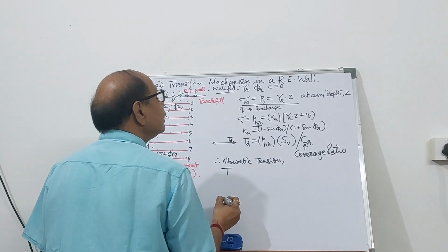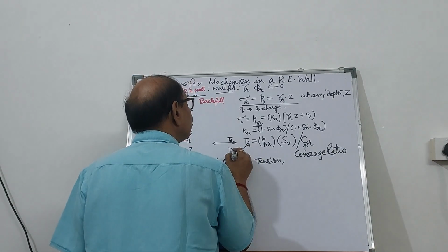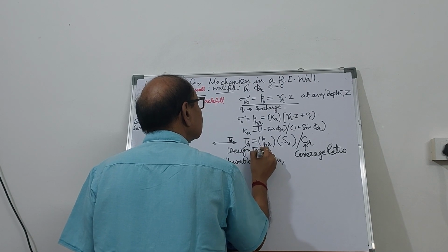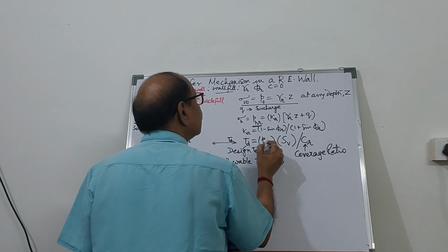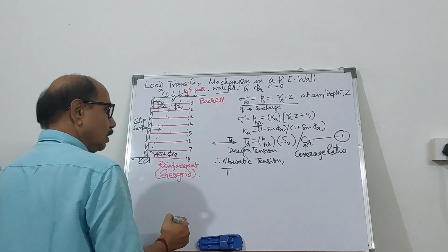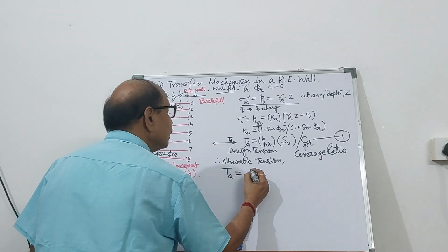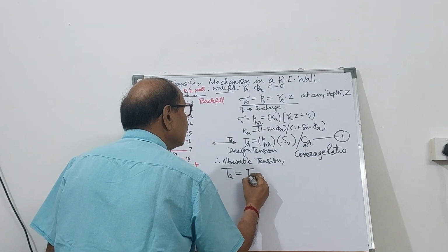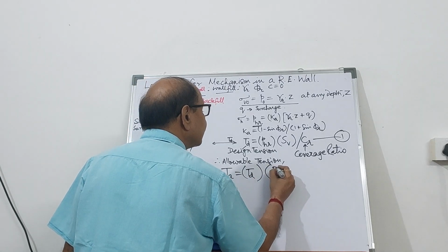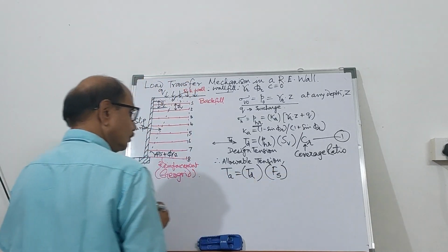This is design tension or tension developed, given by this expression, and T allowable, if you know the tension that is getting developed, multiplied by factor of safety.